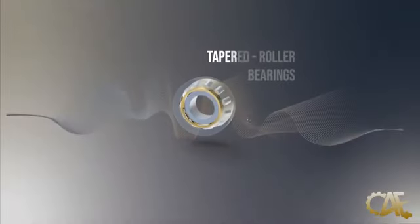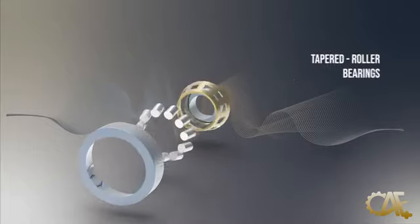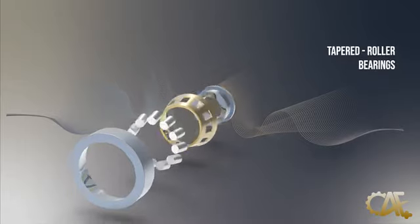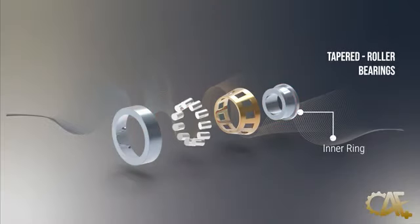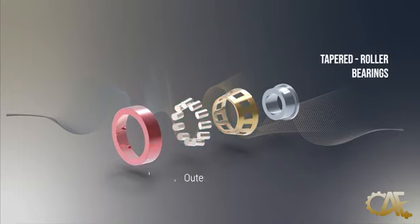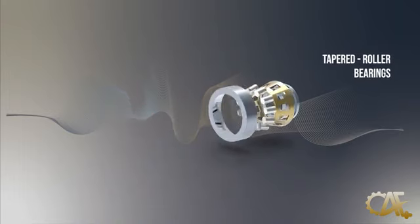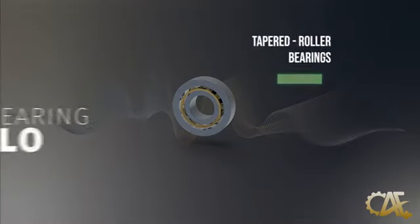Tapered roller bearings consist of tapered rollers, a cage, and 2 tapered inner and outer races. Tapered roller bearings are designed so the inner-outer ring raceway and apex of the tapered rollers intersect at one point on the bearing center line. Their tapered design enables them to support both radial and axial loads effectively. Moreover, they provide smooth and efficient load distribution, reducing the risk of edge stresses and increasing the bearing's longevity and reliability.